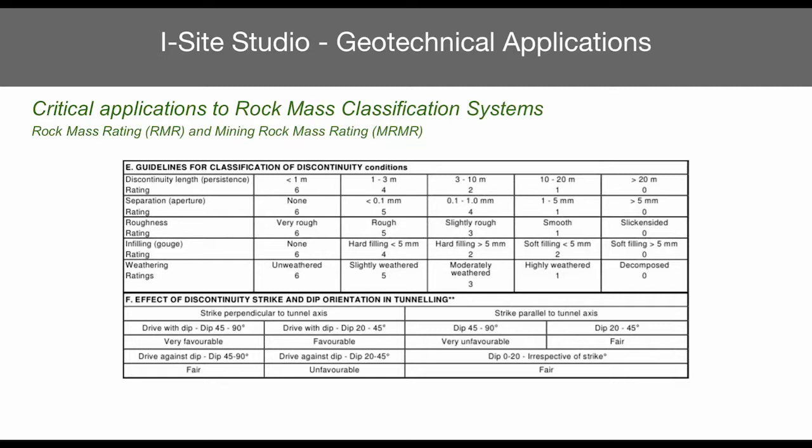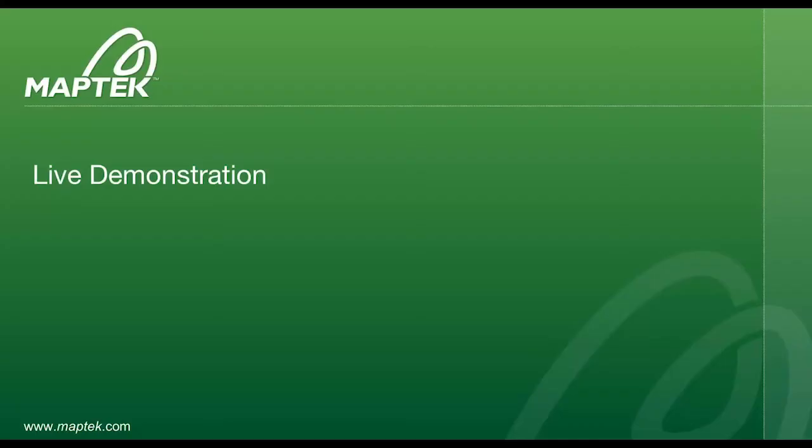I'll also talk a bit on the waviness functionality and the joint propagation to help users predict ground conditions going forward, in an advancing environment. And they can also identify the level of spalling rates, by doing analysis of 2 scans comparison or a scan to a surface. So you look at the spalling rates of side walls or hanging walls over time. So with that, I'm going to pop over to a live demonstration of the actual software.